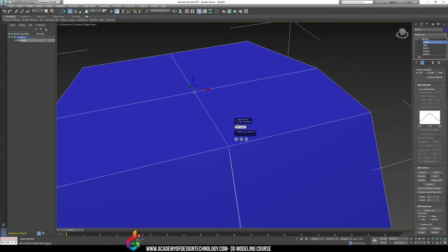If I increase that number, you're going to notice that it previews exactly what happened to our model. Before, there's 34 vertices, and afterwards there'll be 31 if you push apply and continue, or if you push OK. You can cancel out right now, and it won't weld. However, if we go back to weld options, it will say, okay, well, before 34, after 31, with these vertexes selected. If I only had these two end vertexes selected, it would say before 34, after 33.